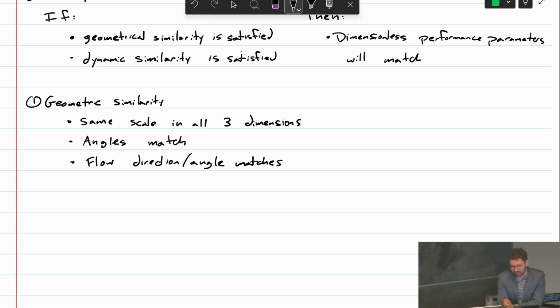In some cases, you might be able to use some sort of symmetry in your design to reduce the complexity or eliminate an axis. For example, you could take your airplane, since it's symmetric, cut it down the middle and mount half of an airplane in the wind tunnel. You might get results that are a little bit different because sometimes there are meandering effects that will be blocked by the wall there. But that's an example where you can simplify the geometry.